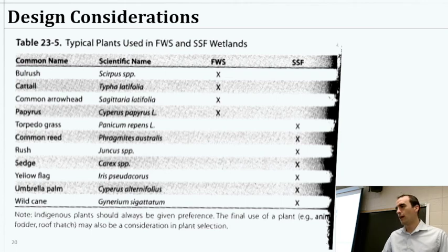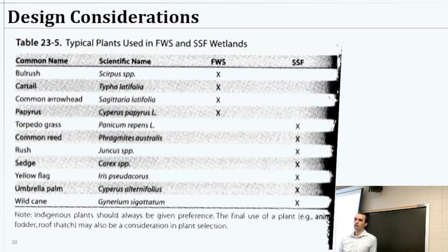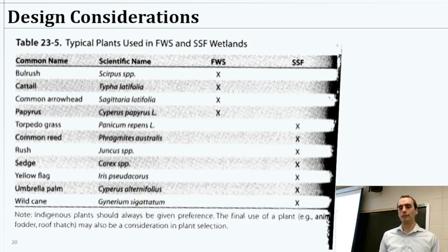A few plants. Of course, if you're thinking about what type of plant to make use of in these different systems, the type of system is going to be very important, because you don't want a plant that can't handle anoxic conditions. You don't want to use that in your free surface water system, because then, like I said earlier, the roots are going to rot and they'll die. Likewise, it tends to be better if you're using the gravel system to have something that can put its roots down deep and just extract as quickly as they can.